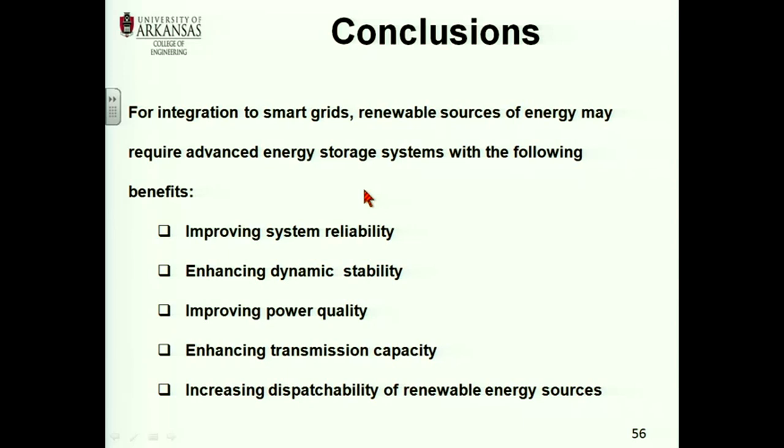Sometimes you can use energy storage for frequency regulation. What's happening if the power increases, or there is a low power and the generator cannot provide that? The generator speed starts going down, and the frequency changes. Frequency has to be kept between 59.7 hertz and 60.2, something like that. Very strict control.